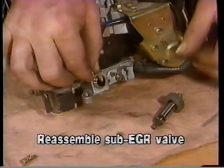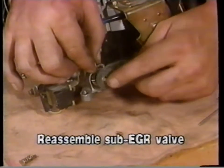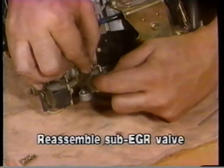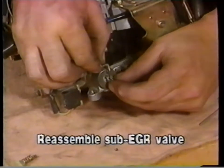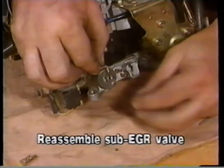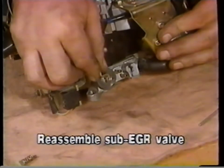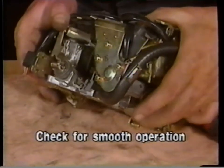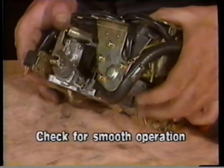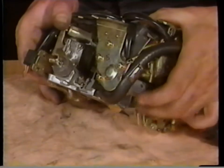After cleaning, thoroughly dry the plunger and bore and reassemble the sub-EGR valve in the reverse order of the disassembly. During reassembly, use the new supplied E-clip from the parts package. If required, a small steel ball has also been included in the parts package. After reassembly, check the sub-EGR valve for smooth operation. If the operation is not smooth, check and clean the throttle and choke linkages as necessary.